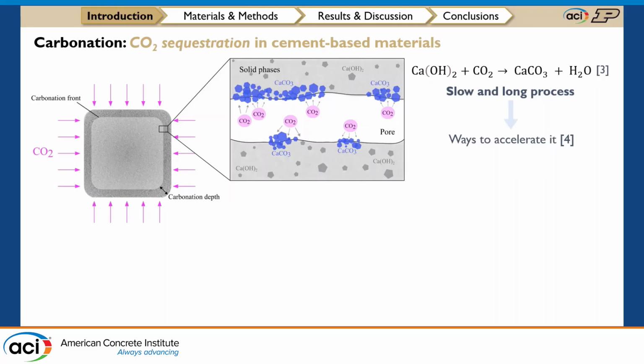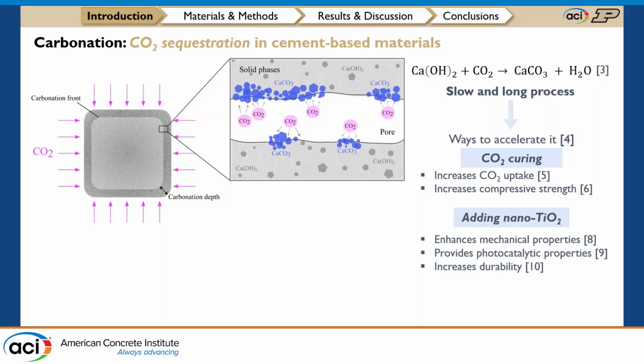So an approach to accelerate this process is to cure our material with CO2. This has proven not only to enhance the CO2 uptake, but also to improve certain properties such as the compressive strength. And also there's a different approach that's been more recent, and that is to add nano titanium dioxide particles into the mixture. So this has been shown to enhance mechanical properties, produce some new properties such as photocatalysis, and also